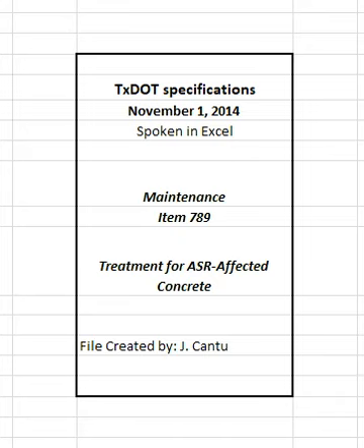4.1 Surface preparation. Prepare all surfaces to be treated to blast finish in accordance with item 427, surface finishes for concrete. Use only abrasive blasting or another approved method to remove all laitance, paint, and other contaminants that may retard or prevent the absorption of the surface treatment material into the concrete or compromise the bond of the crack sealing caulk. Ensure high-pressure water blasting is not used to clean the surfaces.